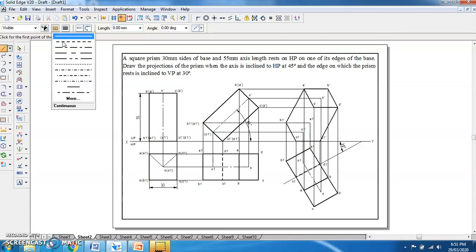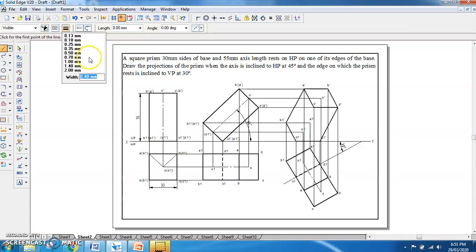So to make invisible, you will be having this type of line, and the thickness would be 0.4. So we'll be connecting this A point, so A point from here, A to this B1 and from A to this D1. Now you have connected this, and this A1 dash is the invisible point. Further, the remaining edges you have to mark. So the edge passing from this hidden point should be hidden. So A1, the edge will be passing through this A1.